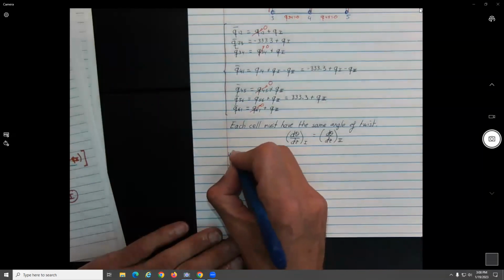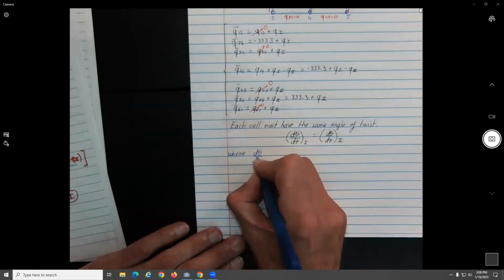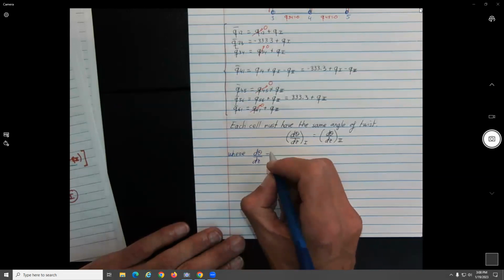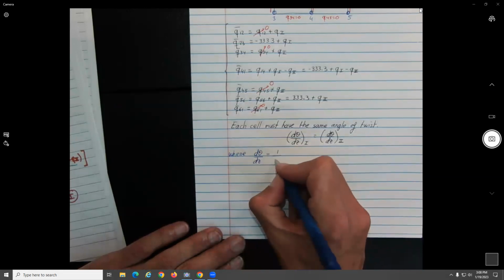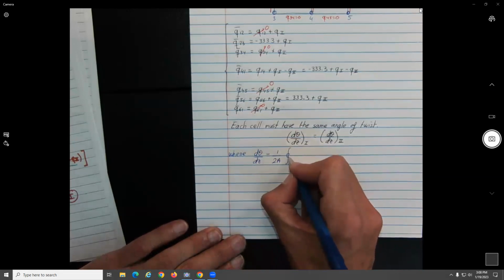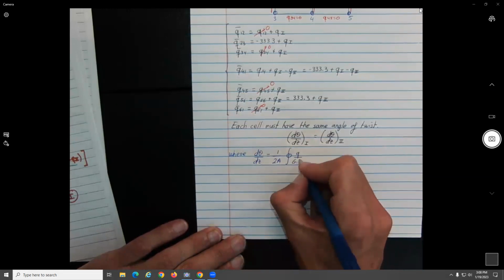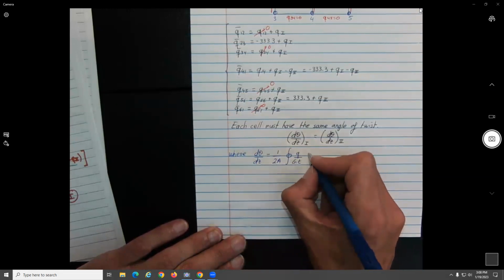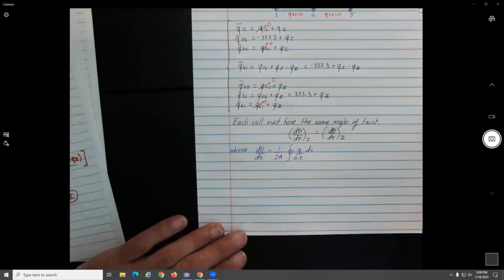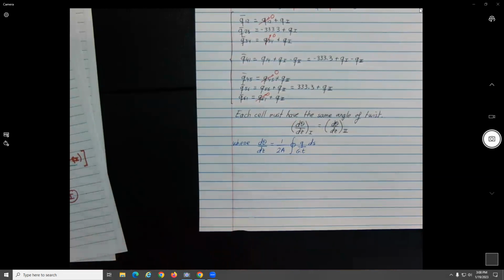Okay, well, just recopying the equation from before, we know that d theta dz is equal to 1 over 2A integral throughout the whole cross section of Q divided by GT. I'm not sure you remember that equation, or if you used that equation in Structures 1. I'm not sure about that. Basically, the angle of twist, okay?